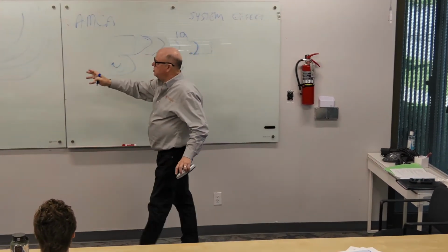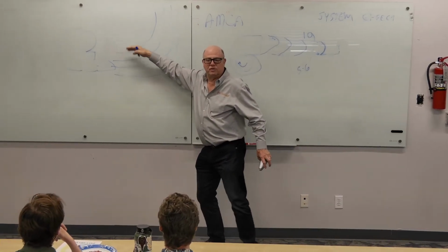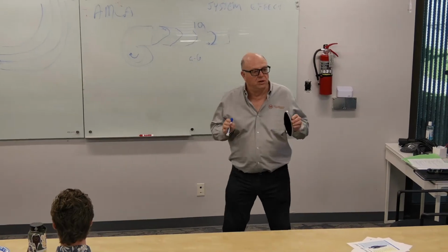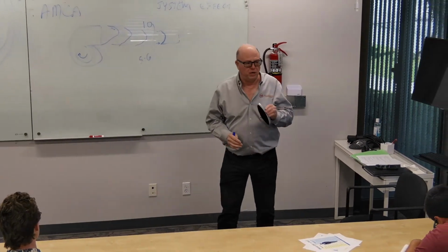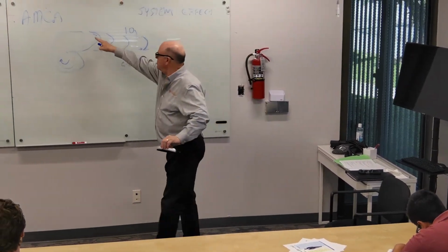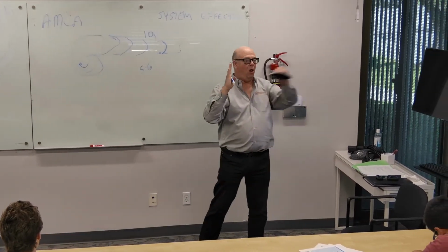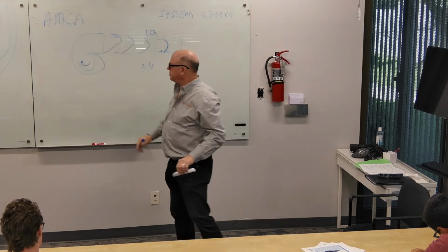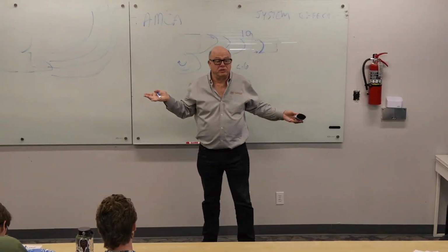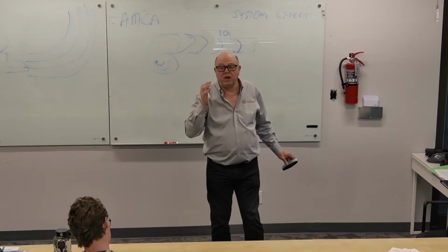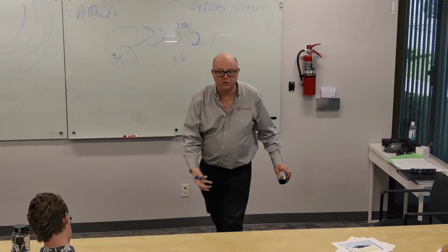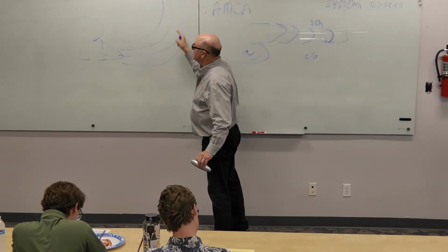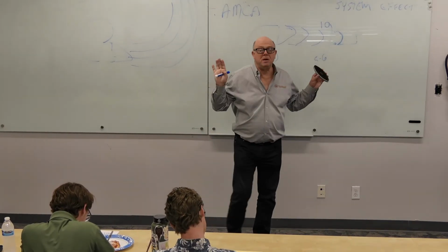But the more you start doing hinky things up here close to the discharge, the more you have changed the velocity and converted it to pressure. Because anytime this velocity of air hits a wall, some of it converts to pressure before it changes direction. That comes at a cost. That comes at a loss of energy, okay? When you've got splitters, you have minimized that.